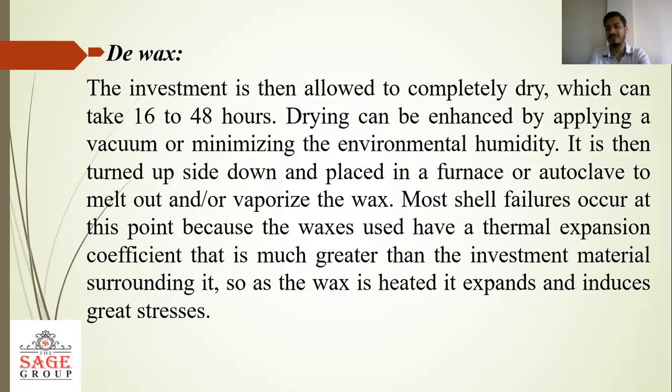Most shell failures occur at this point because the wax used has a thermal expansion coefficient that is much greater than the investment material surrounding it. So when the wax is heated, it expands and induces great stress.